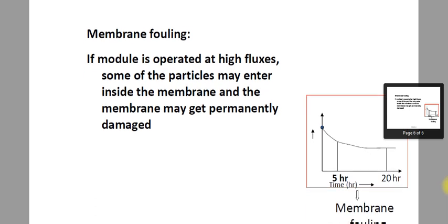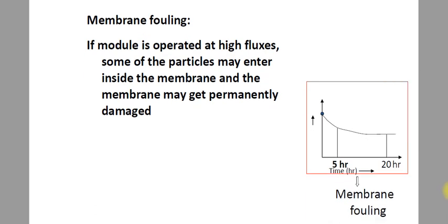Now there is one more technical factor which affects ultrafiltration, that is called membrane fouling. So what is membrane fouling? It is different from concentration polarization or gel formation. Because here you are separating out solid particles, there are chances that solid particles start to insert in the pores of the membrane, and it works on the pore flow model. So suppose the pores of the membrane are blocked due to solid particles, then your flux will reduce with time. So that is called fouling.